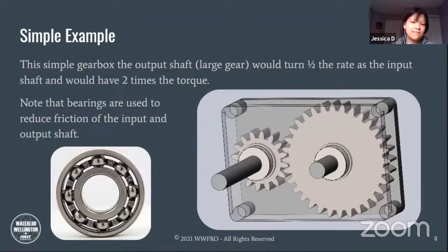So you don't have to count, but let's assume that the first gear has 16 teeth and the second gear has 32 teeth. So the first gear is going to have to turn 2 times for every rotation of that second gear, which gives it a gear reduction of 2 to 1. So the speed of the first gear is obviously 2 times as fast as that of the second gear. So if the speed is doubled, we're going to have to reduce the torque by half on the second one, or on the first one, sorry.